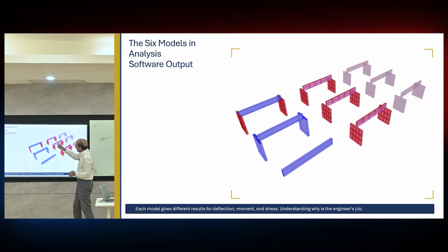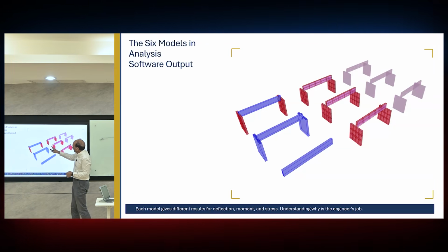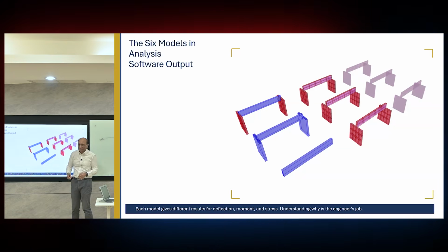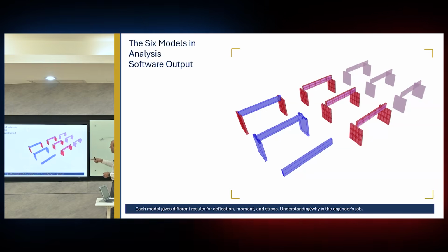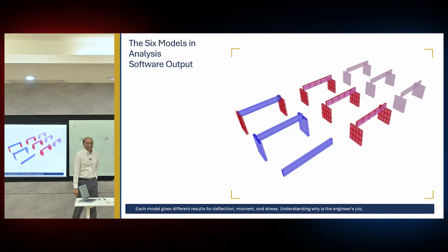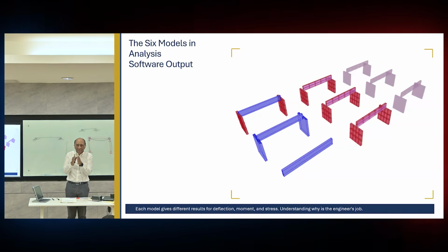Then I say, okay, let me correct it. I move it to the top. I use this also shell. I put it on the top. And then there are different models with different kinds of connections and meshing to connect them together. And then I use solid element. You cannot see the mesh. I use 3 solid elements to match with the thickness, not match with the thickness, and things like that.